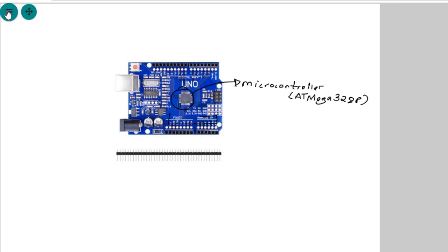It's a long horizontal IC, which is the Atmega328. And the difference between this and this is obviously the P, and this P stands for pico power, which just means that this microcontroller, the one we have on our board, consumes less power than the Atmega328 that you might find in other Uno boards.